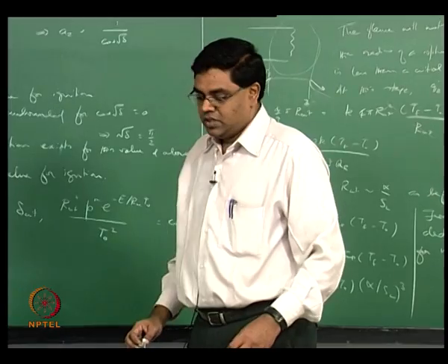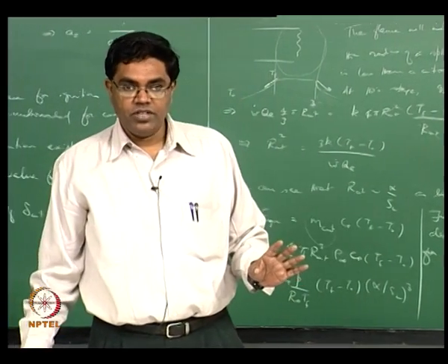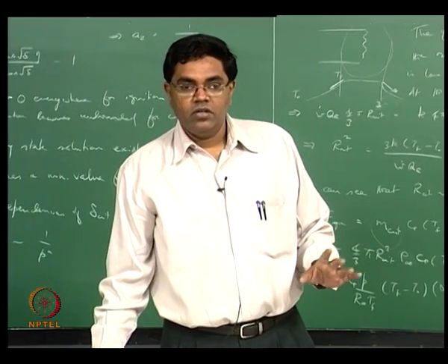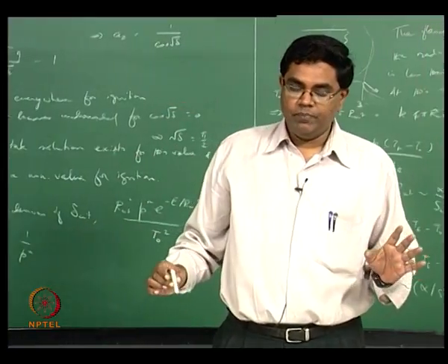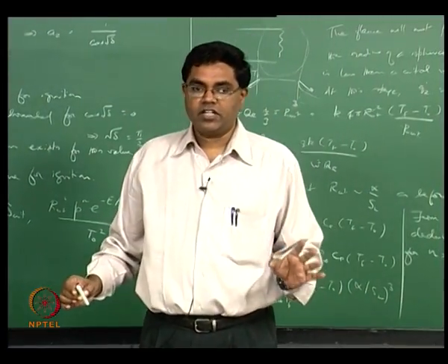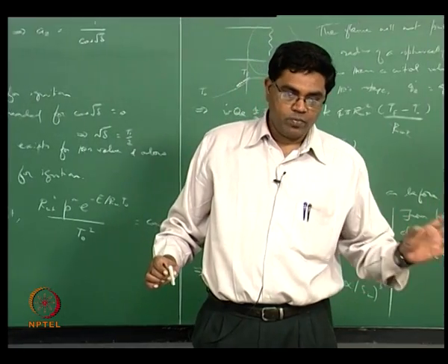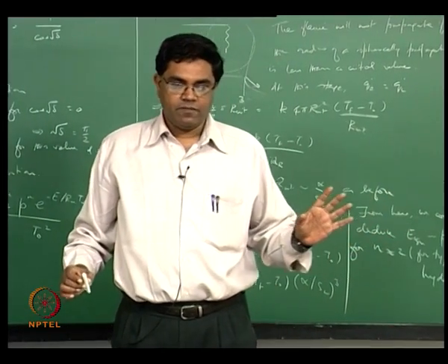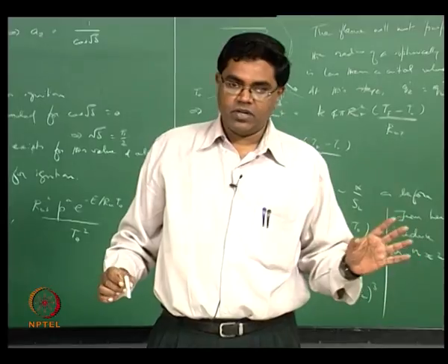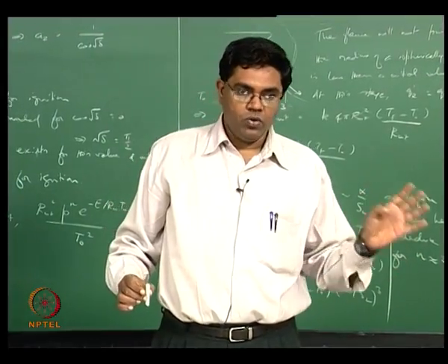We are still primarily in the deflagration regime, that is, we are looking at low subsonic Mach numbers for the reactant flow, and therefore we have to go back and look at the momentum equation and find that the pressure is approximately a constant, because we are now looking at low Mach numbers and low Knudsen numbers.